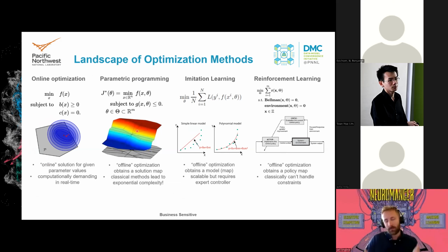We have similar tasks, but before we do so, we want to step back and see how the optimization is being done in each of those domains. Classical model predictive control is solved through online optimization. You formulate or reformulate your problem in nonlinear objective, equality, inequality constraints, and for a given measurement of your parameters that can represent your initial conditions, boundary conditions, or control objectives, you are obtaining a single solution, control decision actions, with iterative solvers like interior point or active set methods.